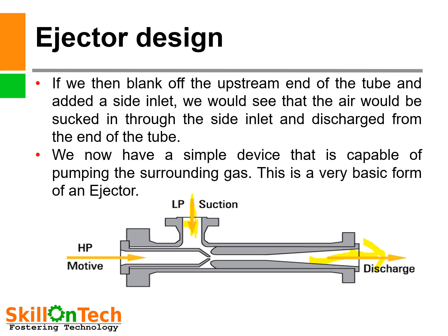So here in this ejector, this is a high pressure motive gas which goes through here. Here it is a nozzle. This pressure energy is converted into kinetic energy, and due to this change, a pressure drop will be there and suction will be from this side, and this will also come along with this jet and be discharged from this diffuser. This portion is called the diffuser. Here the area is increasing and this is the throat.